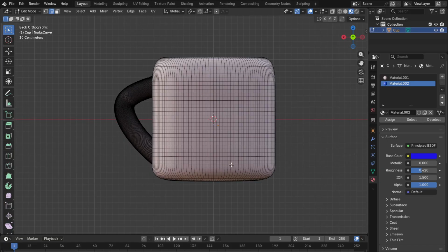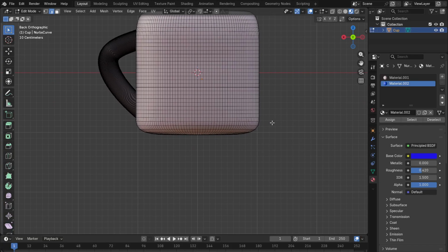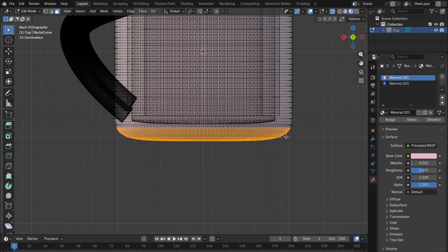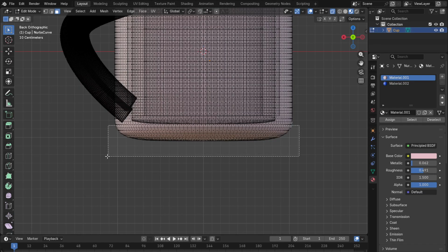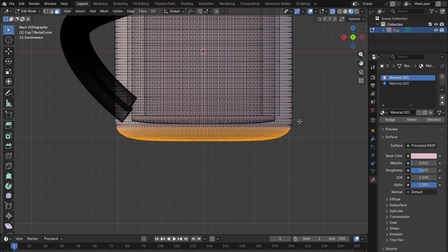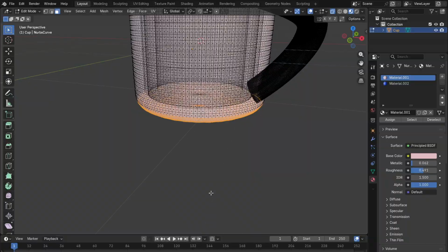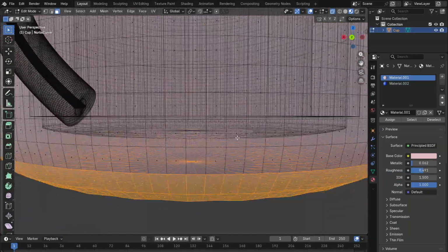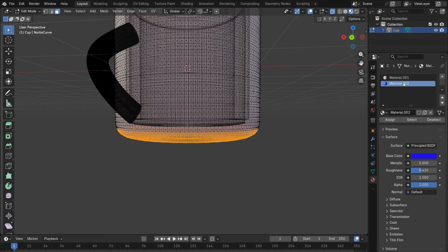And then let's go to the side of the object. It's edit mode, right? See, I have added the modifier, so we have some extra geometry, so we have more flexibility. I'm gonna select this guy, the faces. Go to X-ray, and now I'm gonna be careful what I'm selecting. I'm gonna select only this part. If you're not sure, you can zoom in. See, I missed one line, so select all this line. Make sure that you have selected everything.